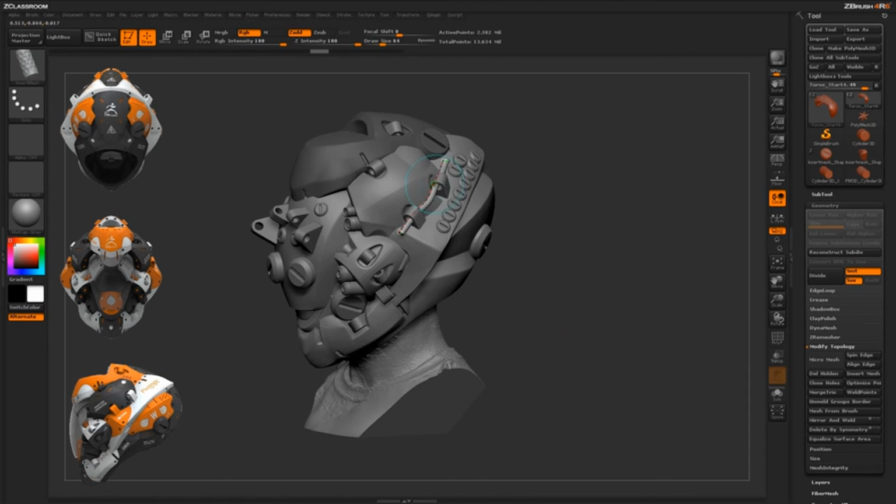Once again, you can save all these out after you have them created by just going to your brush menu up here and going Save As. And you can save all three of the different types of insert meshes. So you can save the ones you can just click and drag. You can save the ones that actually follow a curve and repeat themselves, or the one that you actually need to create a 3 polygroup setup for, a tri-part brush, and it'll take the start and the end and then repeat the middle section along a curve.